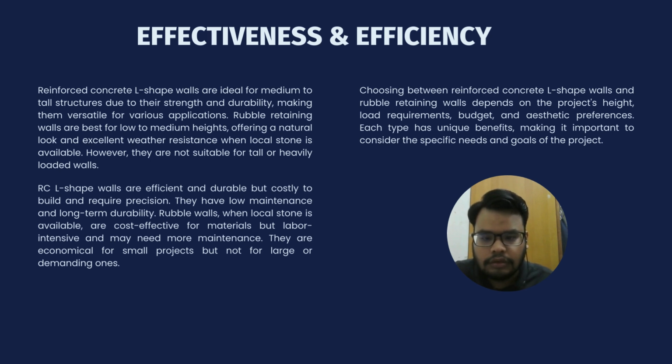Rubble walls, when local stone is available, are cost-effective for material but labor-intensive and may need more maintenance. They are economical for small projects but not for large or demanding ones. Choosing between reinforced concrete L-shaped wall and rubble retaining wall depends on the project height, load requirement, budget, and aesthetic preference. Each type has unique benefits, making it important to consider the specific needs and goals for the project.